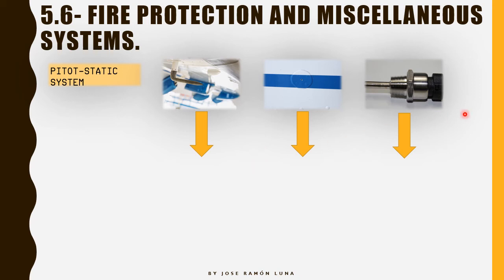The dynamic pressure is going to give us the speed. In the aerodynamics section I will give you the formulas for speed, for lift, for the stall. I'm pretty sure you already know them, but we're just going to be talking a little bit about them. So we talked about the pitot tube, the static port, and the outside air temperature gauge or temperature probe, however you want to call it.